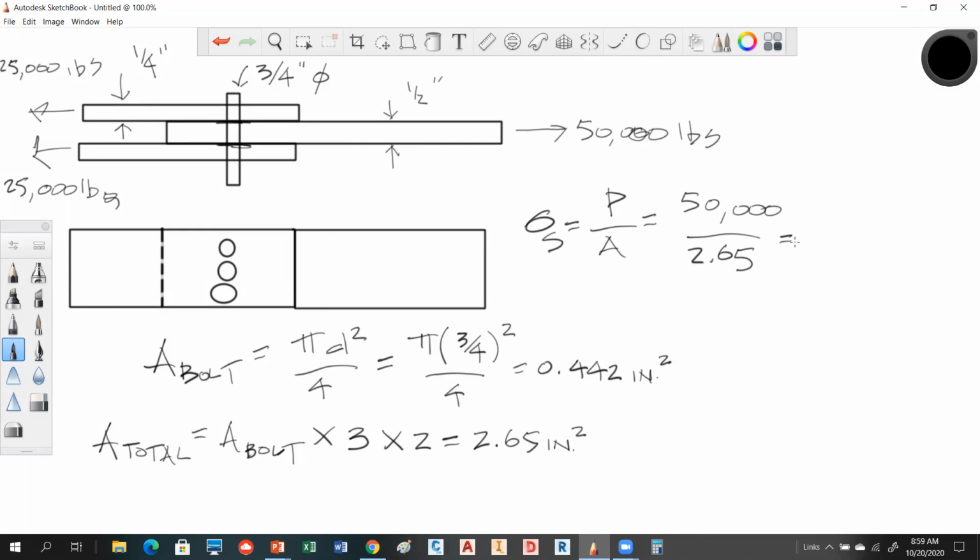So you get like 18,000 something. 18,862. We call that 63 PSI. Everybody seen how that works? Yep. Anybody questions? So what's that last number, that 18,000? That's the amount of stress that develops in these bolts essentially due to the shear force that's being pushed on them. Okay.